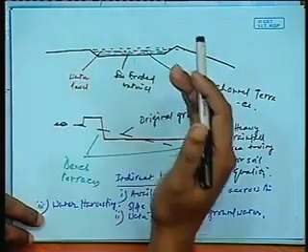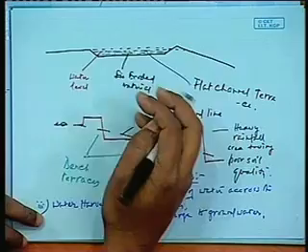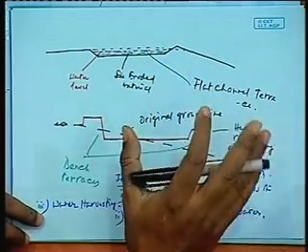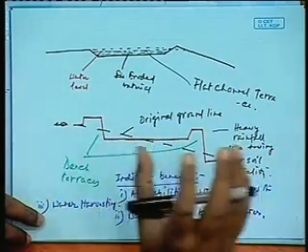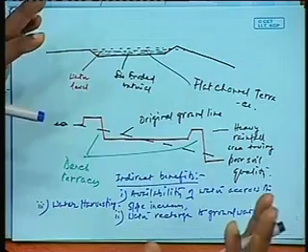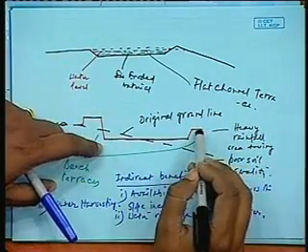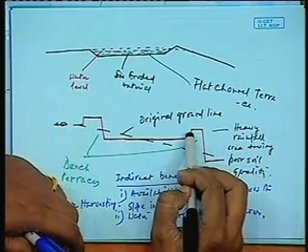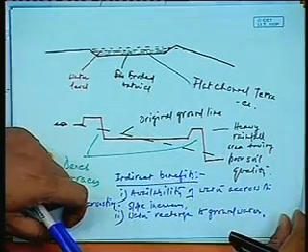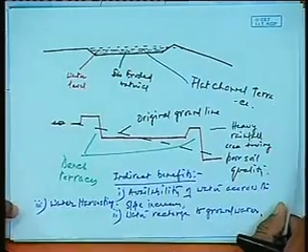Depending on the structure of the slope, the availability of the slope, and the rainfall pattern, you can think of what kind of terraces you are going to have. You should also understand how much rainfall you expect, and what the catchment area should be by which the water can be caught, so that the water does not spill out from the terraces. These design aspects are generally simple in nature, but are also very useful.